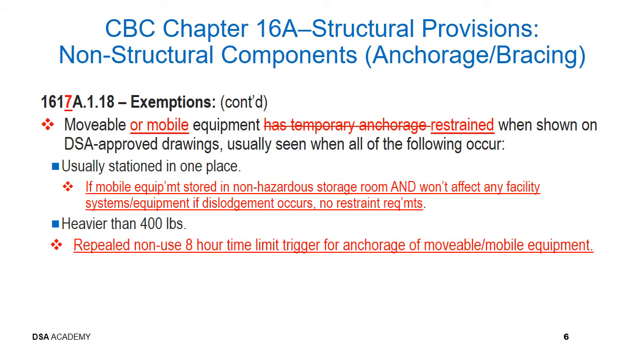B. Movable or mobile equipment which is heavier than 400 pounds or has a center of mass located 4 feet or more above the adjacent floor or roof level that directly supports such equipment shall be restrained.